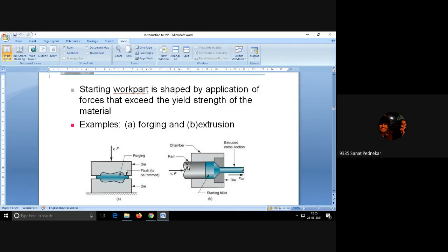Sakib, after sanding, it won't be visible, right? After sanding, but you cannot get a finish. What I had asked was that there should not be any parting line. Any finishing process you use, the parting line can be identified, unless you go for super finishing.